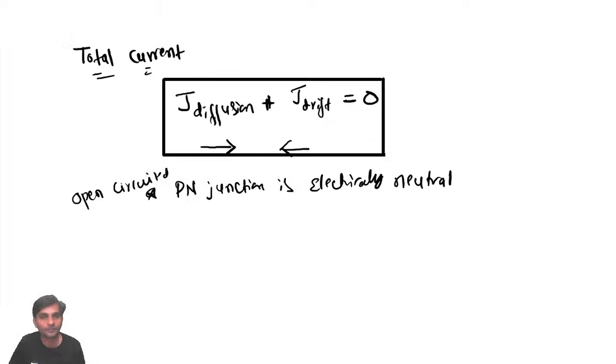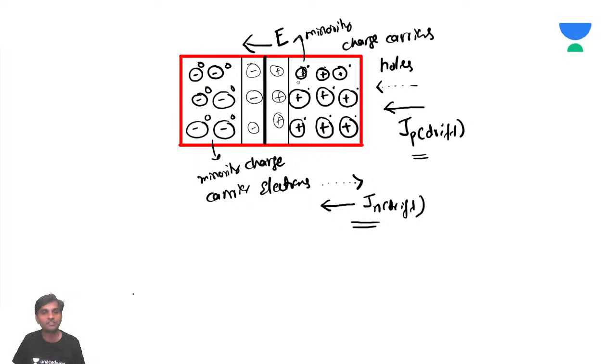Now what happened earlier? Because of this depletion region, these charge carriers are not moving much. Even though, as I told you, drift is existing, that will not make much difference. Drift and diffusion, both of them will be closed. Now what happens at the center? The depletion region is existing, so the charge carriers from one side, if they want to move to the other side, have to jump this wall kind of thing. So they have to cross this region.